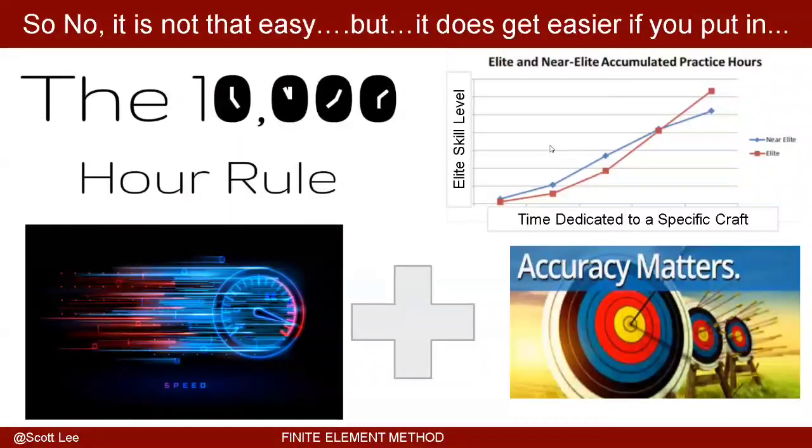And so it's important that prior to really providing answers, you check everything. You can check your boxes and say, my units are consistent, my boundary conditions make sense, I have looked at this. I am an expert at this, but I'm going to have a peer review. I'm going to have somebody else look over my model because I'm too close to it, and I may not be able to see these errors. And I want to say that working on this, I've made errors myself, and having others look over my work can be very valuable. There's nothing wrong with it, and it's something that gets missed a lot. So that's what I would like to add there.